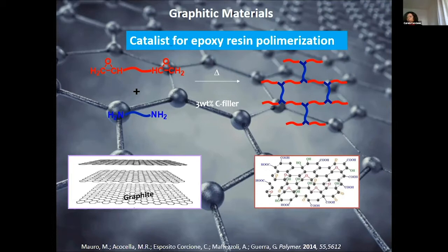In particular, in previous works, a significant effort was directed by the University of Salento team to the preparation of epoxy nanocomposites reinforced with nanographite and to the analysis of their structure, rheological, mechanical, and thermal behavior. Moreover, other additional studies performed by the University of Salerno team in Campania have shown some catalytic activity of graphene oxide layers on the curing reactions of different epoxy resins. In detail, direct kinetic studies with full chemical characterization and quantity evaluation of the low molecular mass products for the reaction of a typical commercial epoxy resin with monoamines as well as with alcohols were conducted at the University of Salerno.